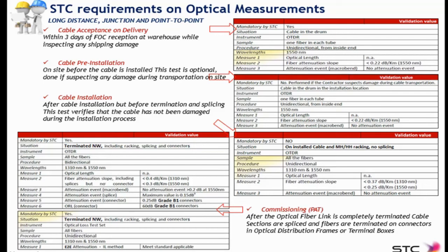The same while installing the cable. Maybe the cable got stuck in the duct and you had to push and pull back and forth. The outer sheath was damaged or the cable kinked and you are suspecting that something went wrong, then this cable installation test is a must. In other cases where the transportation and the cable installation go smoothly, it is optional.